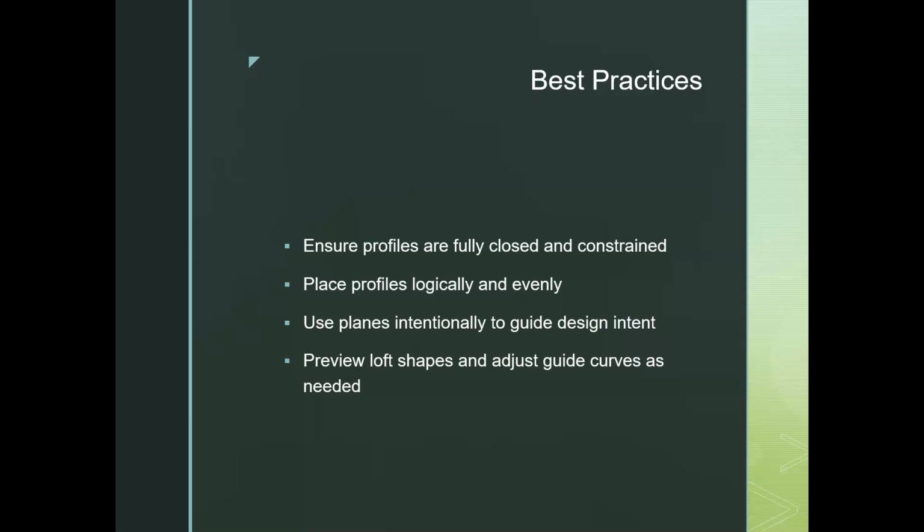Also, if you're using SolidWorks, it does matter where you select those planes. So you're going to see in some of the examples that I do create a Loft in, that I typically like to select the actual sketch out of the design tree, as opposed to actually picking on the sketches inside of my graphics area. And mainly because it will try to give a twist to it, depending on where you select that. So you have to be really careful with that when I'm using that in SolidWorks.